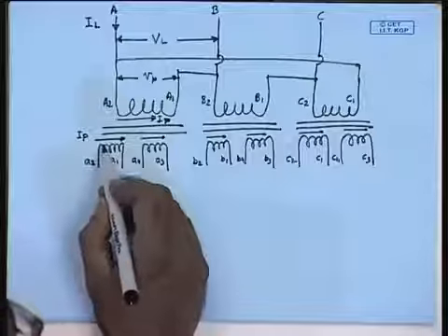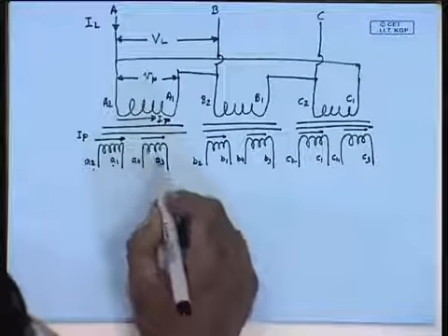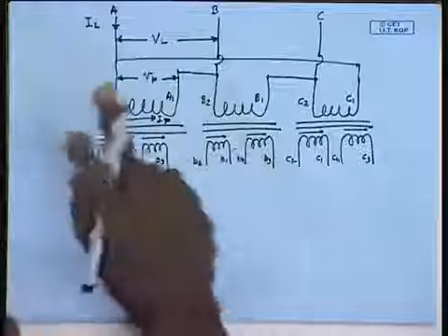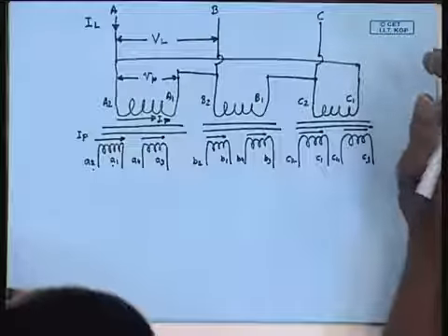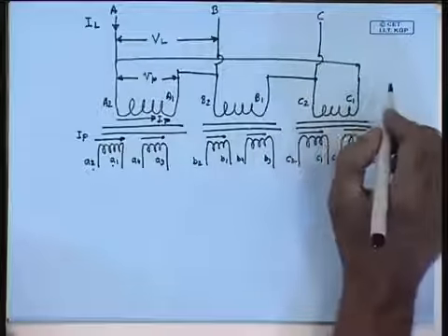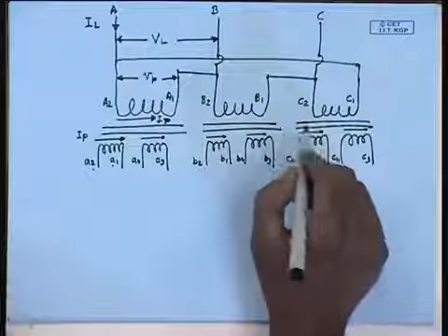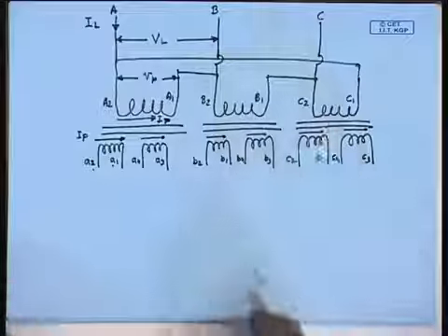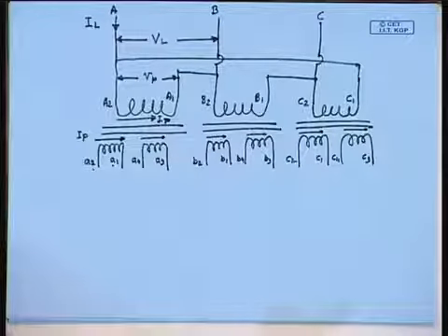This current I will call I A2 A1, this is I A4 A3, this is I B2 B1, that is from B2 to B1. In order to make a zigzag connection, one of these sets of windings is star connected.